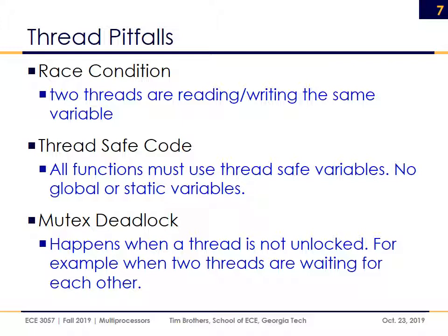Race conditions. These are possible pitfalls, things that can now go wrong if you're doing multi-threaded. We talked about this before at different levels. Each new level of hierarchy that we add into the architecture creates the possibility for new pitfalls. For instance, when we were talking about the CPU architecture and we just had single cycle operation, that meant that one command was going to be processed through the fetch, decode, execute, memory, and write back stages. So the time it took to get through that entire process was one clock cycle.